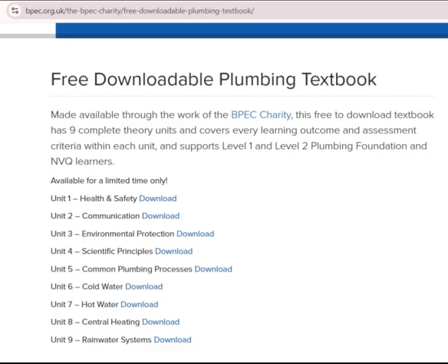The application of pressure and flow rate measurements. Pressure and flow rate are the key points that any plumbing system will be measured by. If the flow rate or the pressure is poor, then this can be the result of poor design, poor installation or both. Good plumbing design and installation will deliver the desired pressure and flow rate for a given specification. However, we must also be aware that too much pressure or too high a flow rate can be detrimental, as they can cause noise and erosion problems in pipework and fittings, and this may lead to breakdown or failure of the pipework or components. In heating systems, too much flow rate can be detrimental, as this causes unwanted noise. We will examine pressure and flow rate later in this section.